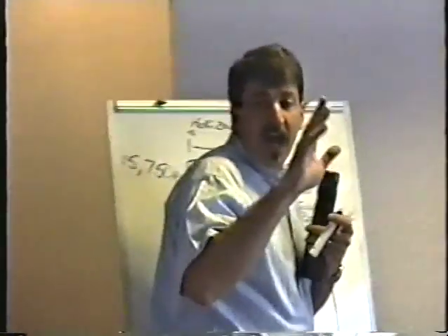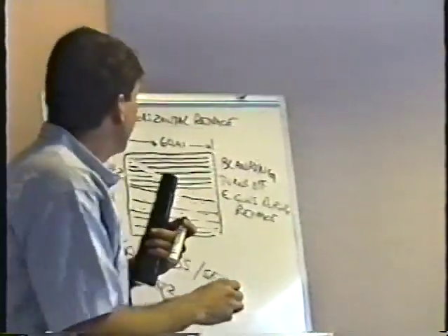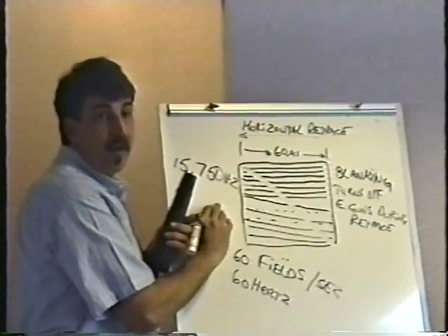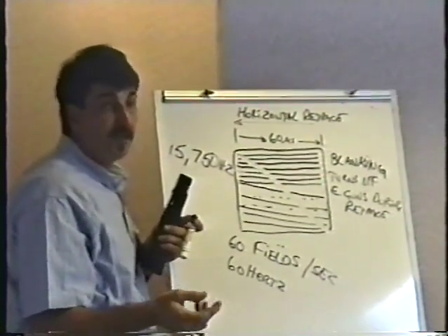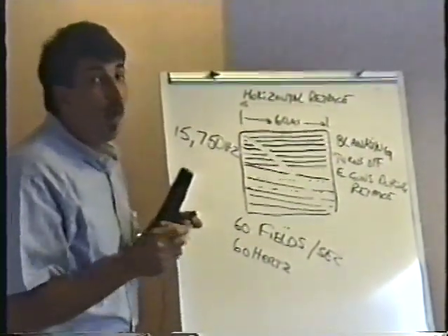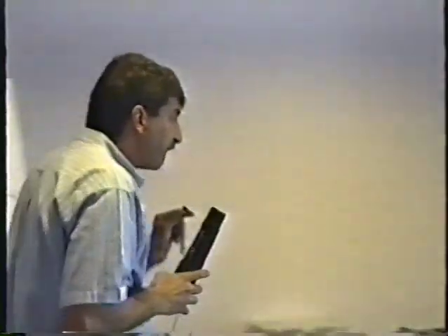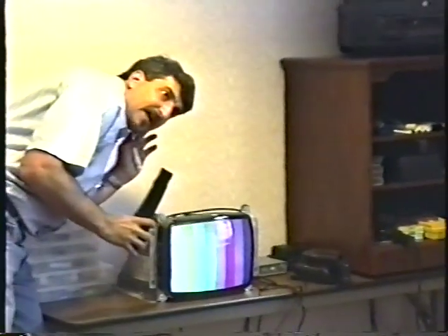How many of you can hear that high-pitched squeal that a monitor makes when it's on? Let me see your hands if you can hear it. Okay. If you can hear that sound, what you're hearing is the horizontal frequency. You're hearing the 15,750 cycles per second. Whenever I turn on a monitor, I always listen for that squeal because it tells me that certain things are working.